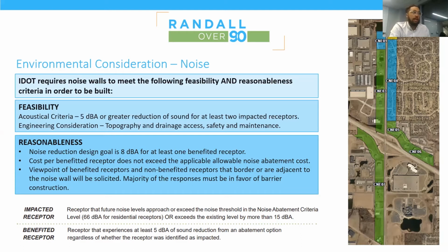So when a loud semi truck goes by, it goes up to, let's say, 75 decibels or something. That number will not be the number you use to say what the sound level is from the roadway. That might be a maximum sound level that you observe, but you end up taking an average over an hour of what that sound level is. So it's not exactly a constant sound level, but it is an average over an hourly time period.